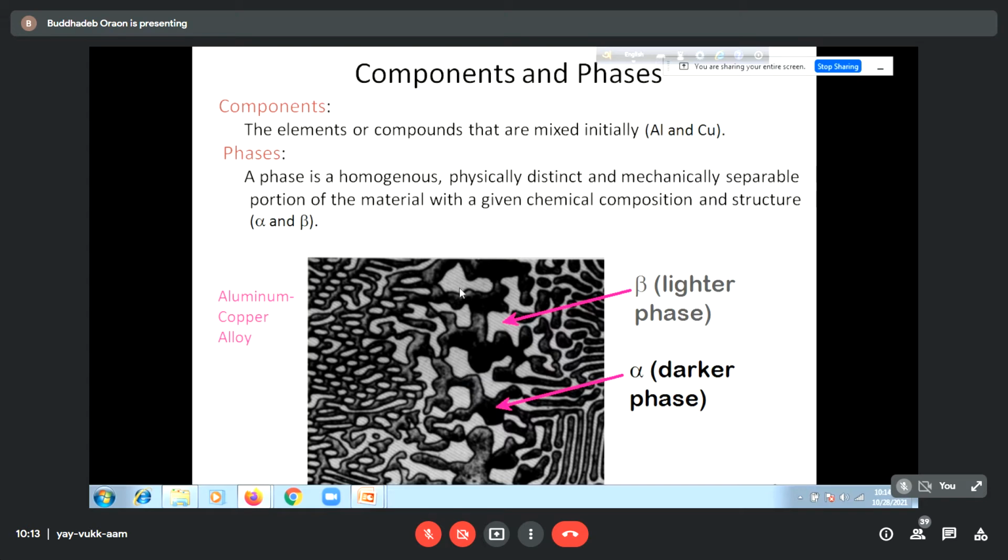So this is one diagram where we can see the two important phases in the microstructure. So the whole diagram is called the microstructure of copper aluminum alloy. So what are the microstructures you can see? We can see the microstructure of beta phase and we can see the microstructure of alpha phase. We are typically terming these two different phases, solid phases, alpha and beta phase.